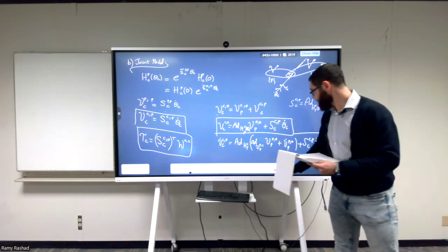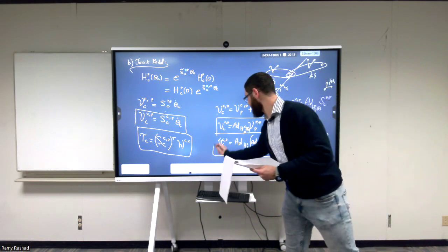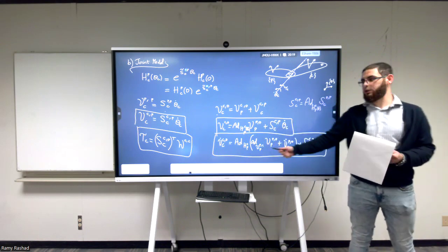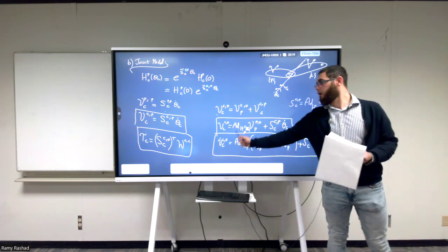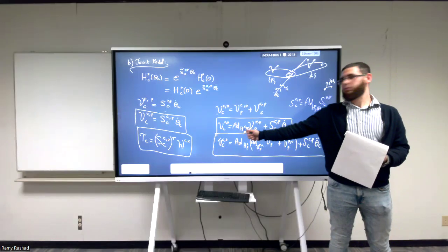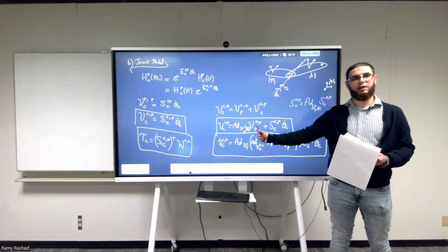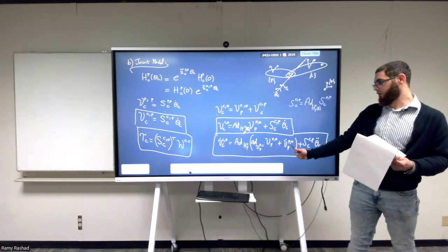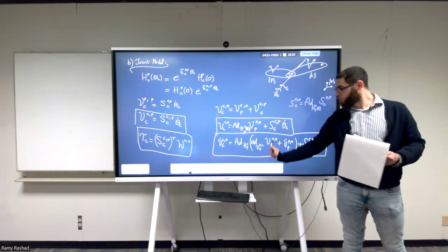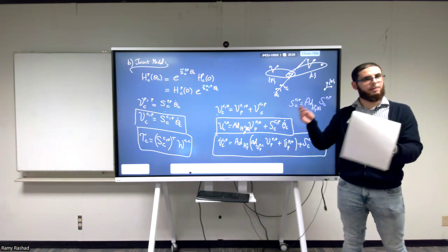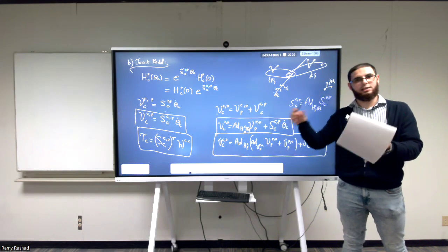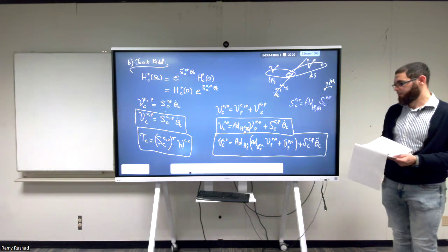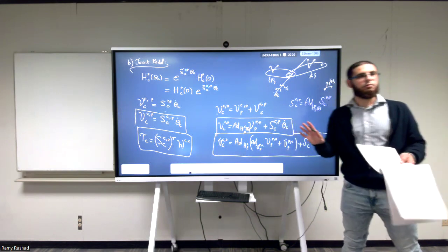Yeah, okay, that's it. This is everything we need to talk about the dynamics. You see, I have a closed form expression for V dot, a closed form expression for the V, and they depend on the theta dot and the V. And of course, this one is an acceleration, so there's an acceleration term here. There's some adjoint between the two twists. So you can imagine that this adjoint of two twists gives us something like an acceleration. And we have here an acceleration term in terms of the theta. That's it. So we're done.